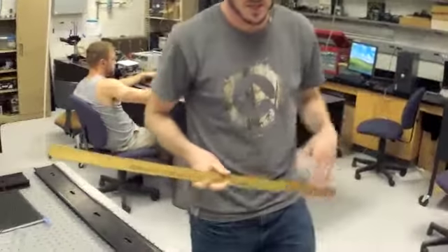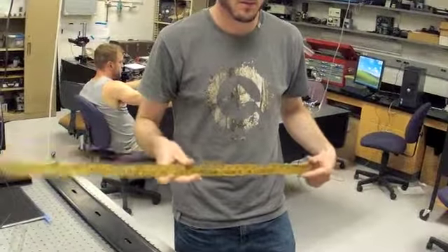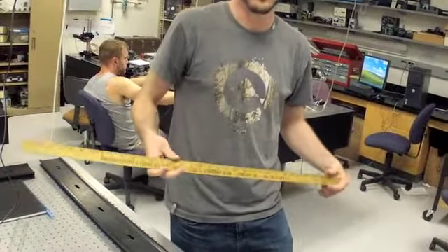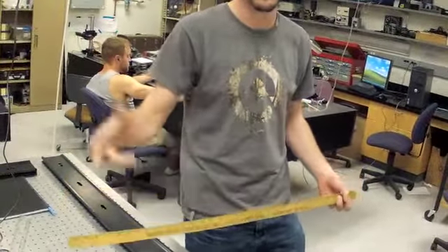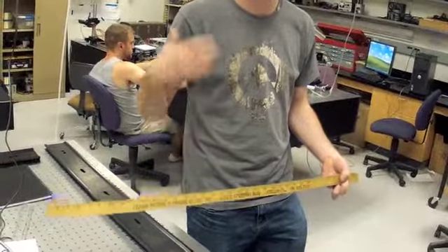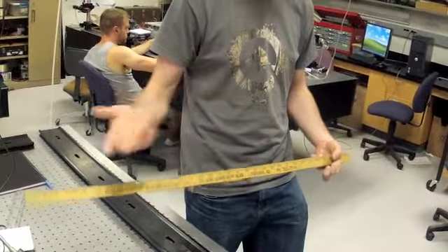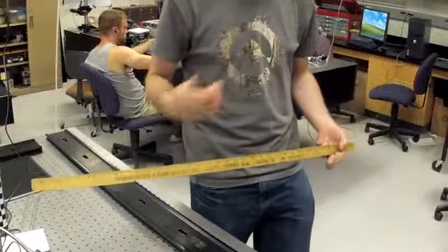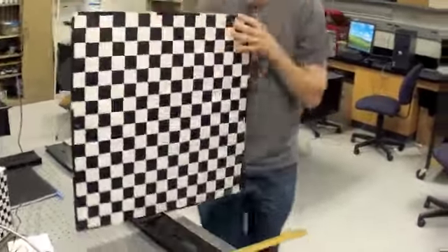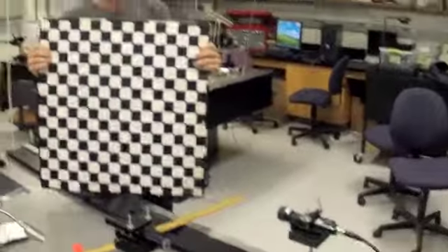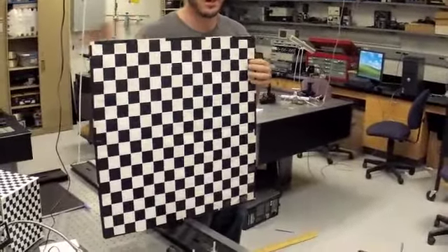For the next part of the lab, we had to measure the horizontal and vertical field of view. To do this, we took a meter stick and put it at the full frame of the field of view, and based on this, we can get the field of view and angles by knowing the distance to the meter stick. From there, we took 20 different images of the checkerboard at different orientations in order to get more accurate data.